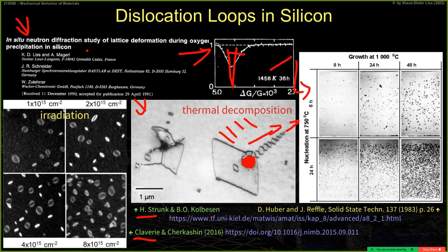When you have, for example, a surface or a silicon wafer shown here in vacuum, then you have oxygen, and the oxygen, you all had the diffusion course, so you get a depletion of oxygen near the surface. And here near the surface is this depletion of oxygen through degassing into the vacuum. You have done that in the diffusion course. And then at longer time scales you get precipitations where you have oxygen.